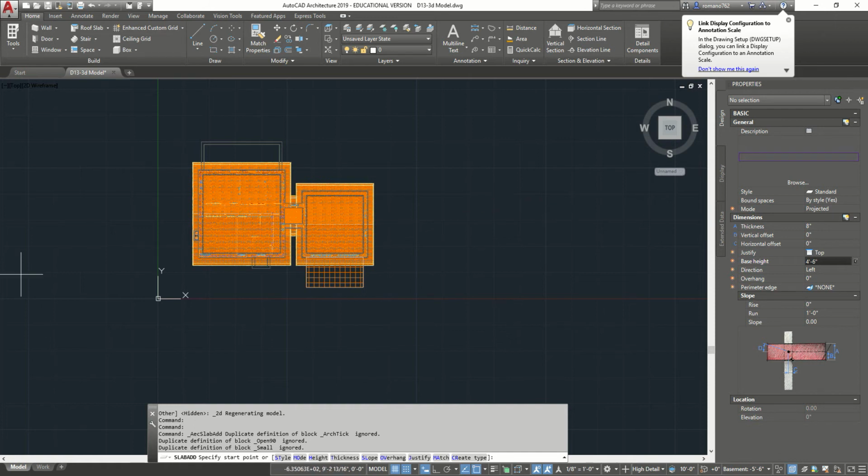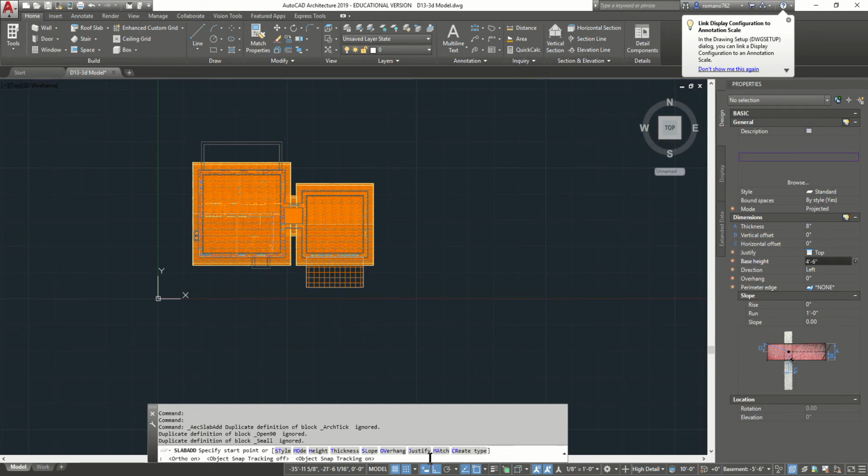Alright? Now that that's done, we're going to draw a rectangle around our object. To make sure you have straight lines, you can use the ortho, which is F8. Turn that on. And you can use object tracking, which is F11. We're going to make the shape of our building, like we've done before. Make sure you pass the actual building.